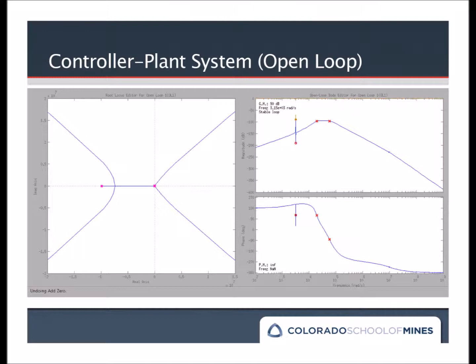The next step was to use a pair of complex poles to effectively undo the slope increase created by the zeros and give us a flat magnitude plot across our passband. Finally, we placed another set of complex poles at the end of our passband to attenuate any signals at frequencies greater than our 8 kHz threshold.